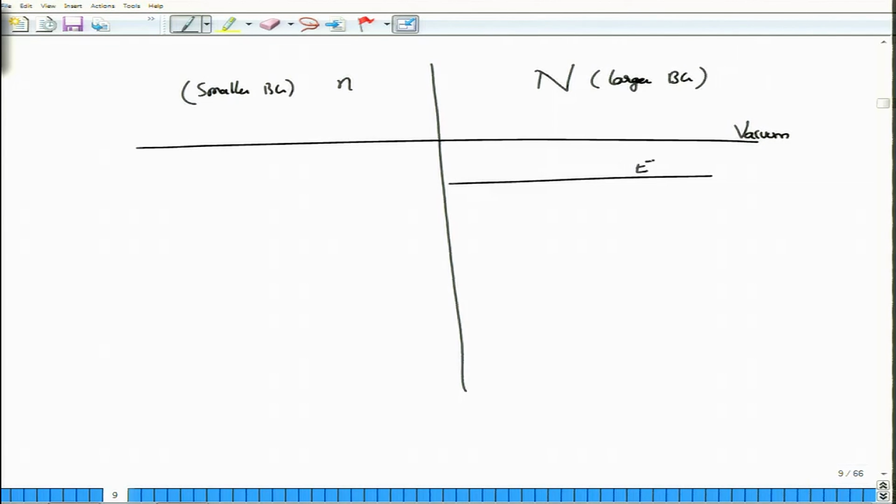I should not write it very close to the junction because the property will change. So, I am going to write here, and this would be my conduction band, which I would call EC2. Of course, this distance between the vacuum level and the top of the conduction band is the affinity chi 2. Okay. The smaller the affinity, the smaller the energy required for the electrons to be removed from that particular material. Please keep that in mind, that is very important.